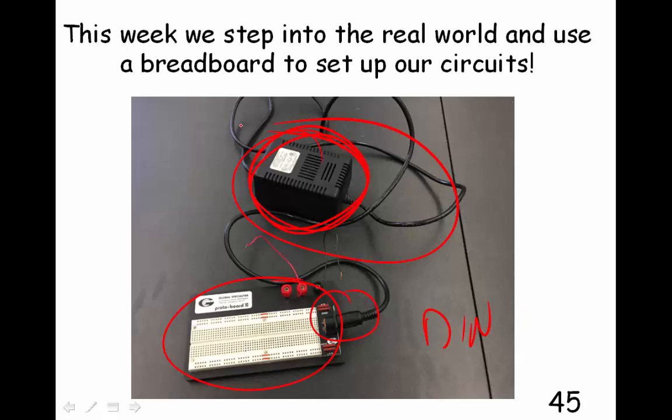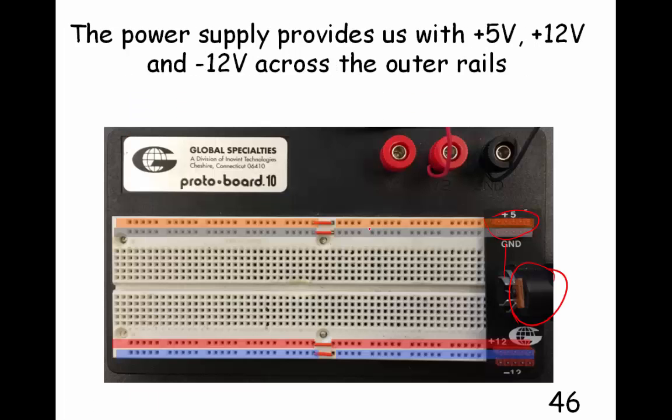And you're going to learn how to create your own power supply in this class. What's in this black box, you don't know now, but you will eventually. So what comes out of this is 5 volts across this rail. They have to use a little jumper here because these are all connected, these are all connected, but then you need a jumper to connect that across. So every wire you connect in one of those little holes will be at +5.